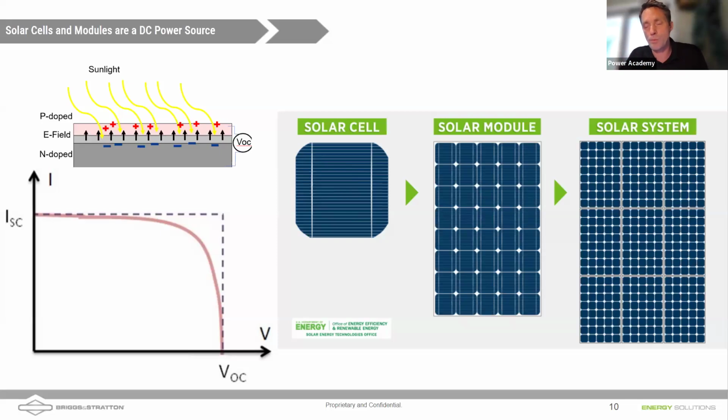So when you produce this DC electricity with a solar panel, you put a bunch of cells in series within that module to up the voltage, and then you put a number of modules in parallel or series, right? Often it's strings of cells that are in series with a DC system to get your voltage up to higher voltages. Higher voltages, less amount of current overall, are more efficient ways to run electricity. And so if you're running a solar array a long distance from your charge controller, highly encourage you to use the upper voltage range of the MPPTs.